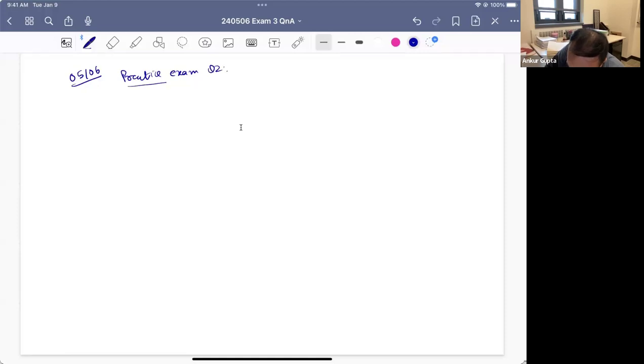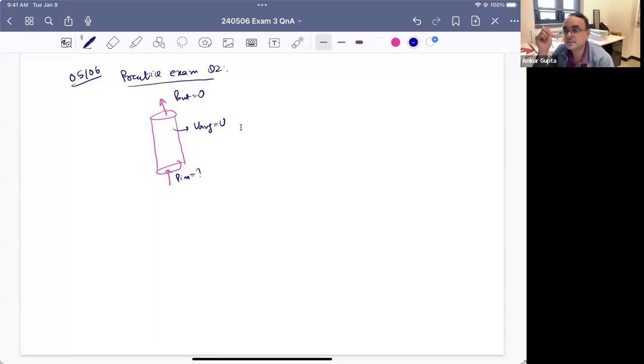question 2. So basically, the problem is asking what happens if we are pushing some water up a vertical pipe. The outlet pressure P out is 0. P in is something we are being asked to graph. And the velocity is given as U. U average is U. And the flow is under laminar condition, and which of the following plots describe the relationship between P and U. So first, this is not a horizontal straight pipe, so we should use Bernoulli's equation.